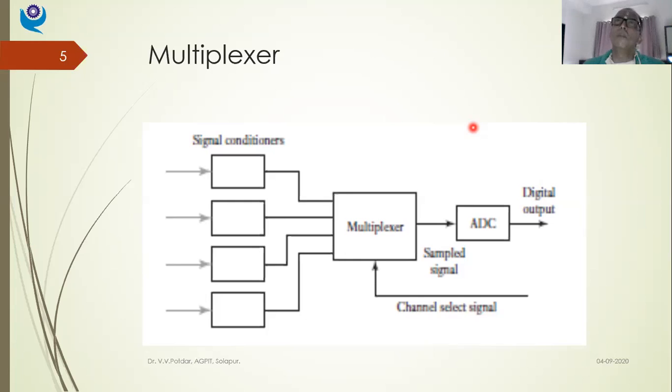If you remember in the heat transfer lab, whatever was the experiment, maybe thermal conductivity of a powder or composite wall experiment, there were different thermocouples used, isn't it? But there was only one signal conditioning device. You used a toggle switch. You toggled from the first thermocouple to the second to measure the temperature, and that analog signal was getting converted. For that switching position, I used to get the converted signal in digital form. So this sort of toggling, which we did mechanically there, this multiplexer will do